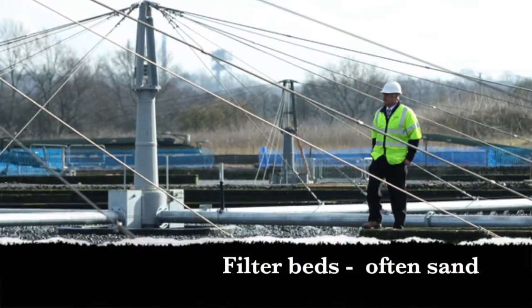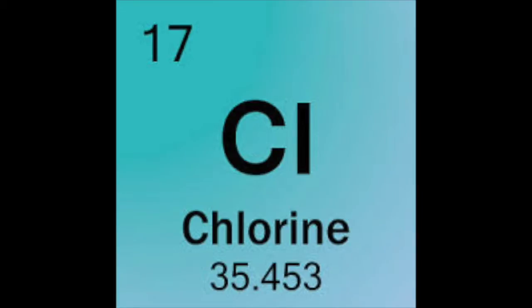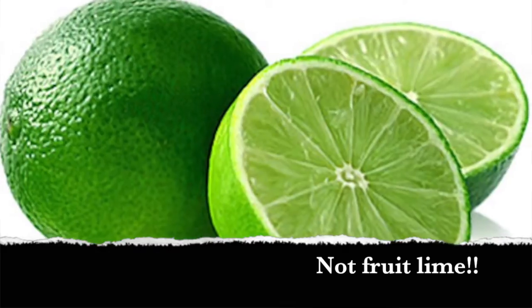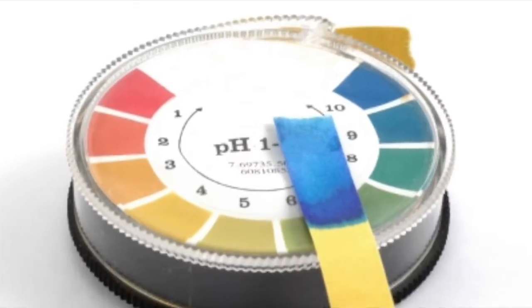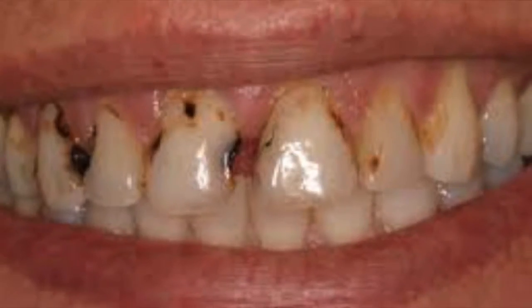4. Water goes through the filter beds, often made of sand, where the floc is caught and clear water filters out. 5. Disinfection. Chlorine is added, and sometimes ammonia, to destroy microorganisms that could cause illnesses. 6. Other chemicals like lime, carbon dioxide, sodium hydroxide, and sulfuric acid may be added in small amounts to improve the safety, pH, and taste of water. 7. Fluoridation. Fluoride is added as required by New South Wales law to prevent tooth decay.